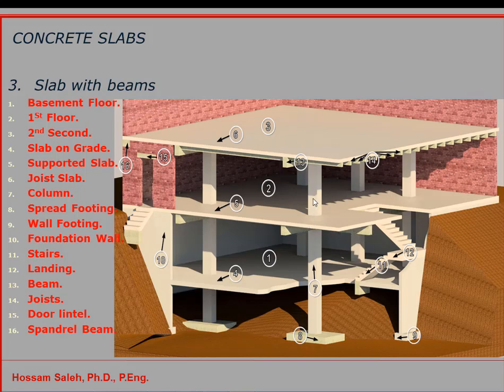And if you go to the upper level through the columns, you can have the floor or the roof, and this roof is supported on small beams next to each other. We call them floor joists, and the Canadian code specifies the distance between the floor joists to be not more than 800 millimeter, and they have a specific designation or a specific design for that. These joists normally are supported on girders or beams at the end, as you can see.